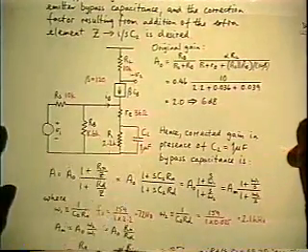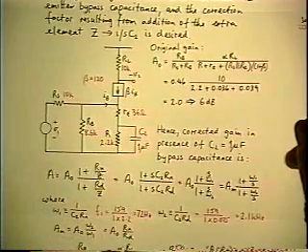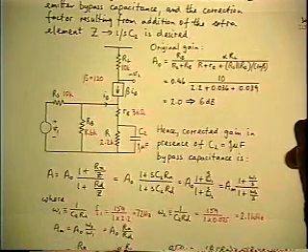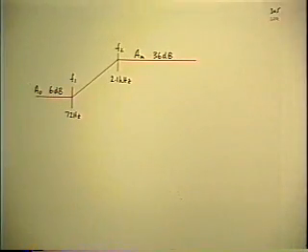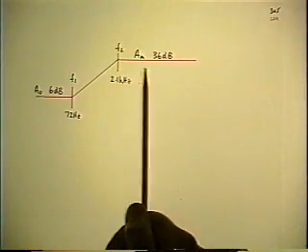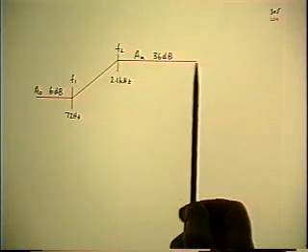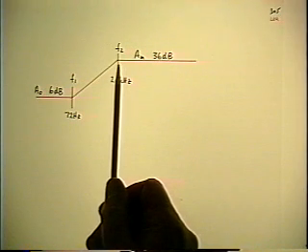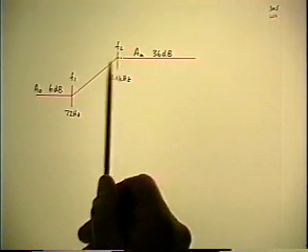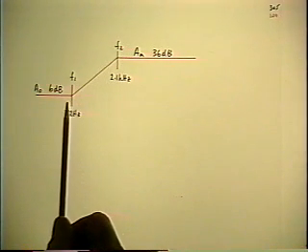And the bypass capacitor there is simply to eliminate the effect of the R as far as the main gain and frequency response is concerned. So the high value of gain that you get is the one that you have to meet the specification with. You also have to meet the specification for this corner frequency, because you have to maintain this gain down to some specified value, and there probably isn't even a spec at all on the other one.